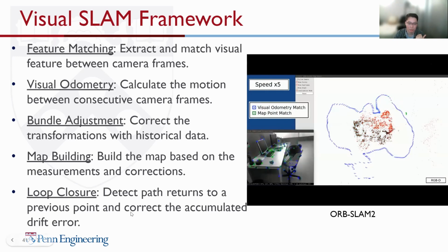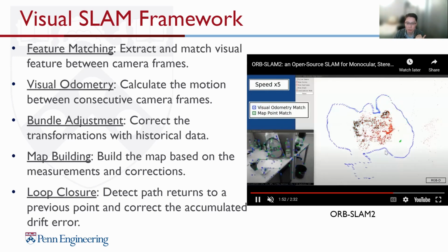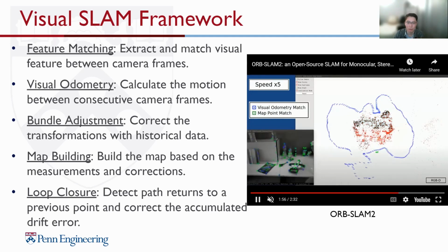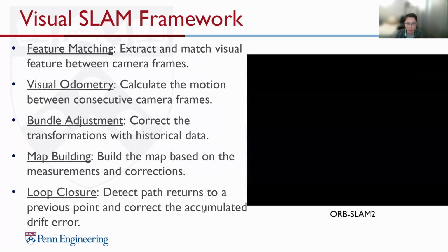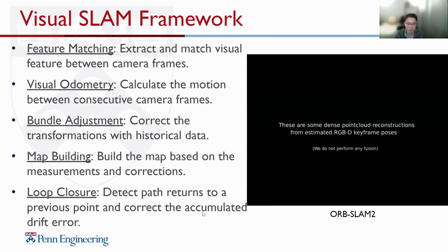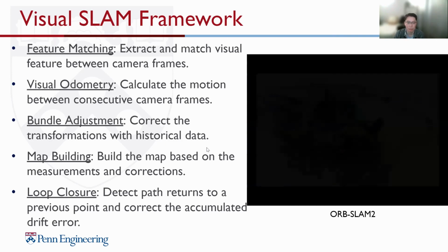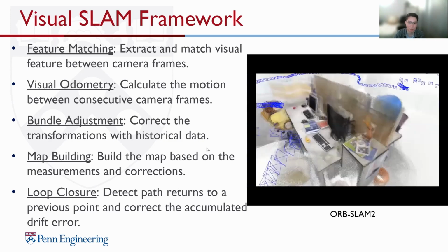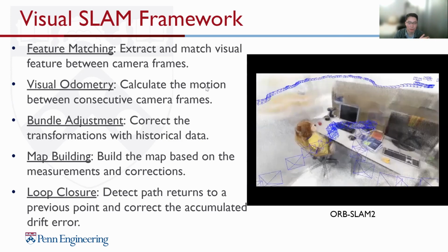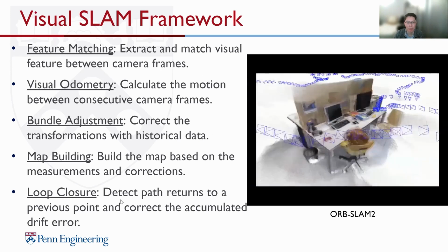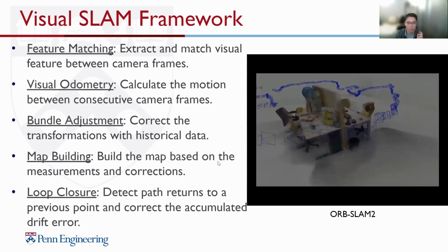Usually you're able to do local detections very well, but your paths may just drift over time. So when you come back, your odometry probably shows that you are not in the same position. Can your vision part correct it by doing this loop closure?